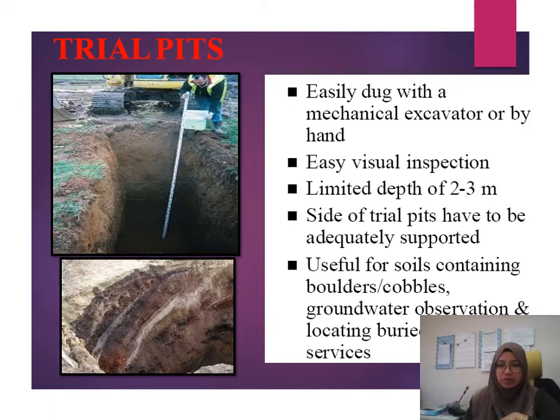But if the soil is very soft, you have to provide something to support the exposed soil. It is useful for soil containing boulders and cobbles, groundwater observation, and locating buried services and so on.